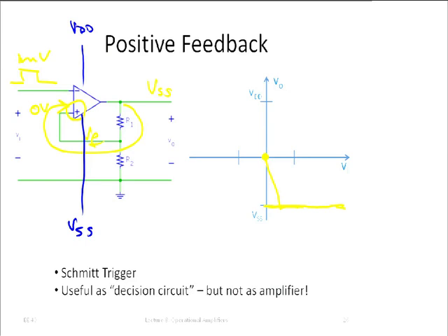Then the voltage here, anyways, is still positive, right? Voltage here is still larger than 0 at the positive terminal of the op-amp. So we have a voltage that is larger than 0. Again, perhaps it's VSS over 2. And we subtract from it now the new input voltage that is 0 volts. What do we get? Still a positive voltage, right? We amplify this by a very large factor, and the operational amplifier is going to, sometimes the term is used, rail. It's going to rail at the negative supply, and it's going to be stuck there, right?